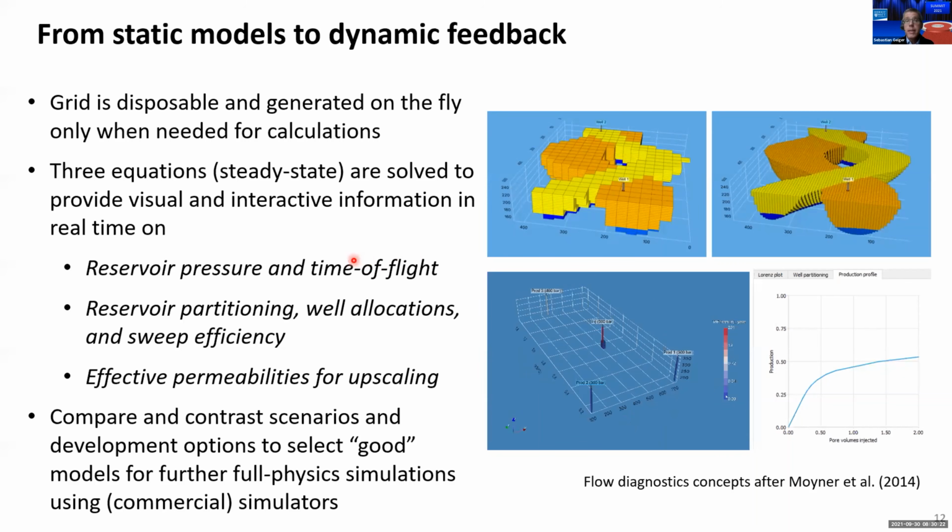We solve steady-state equations to provide visual and interactive information in nearly real time on the reservoir pressure, time of flight, the reservoir partitioning, well allocation factors, and sweep efficiency, and we also do flow-based upscaling for effective permeabilities. Essentially, we've implemented the seminal work that came out of SINTEF by Olav Møyner, Knut-Andreas Lie, and others into RRM around flow diagnostics on grids. This allows us, as we're building geological models and testing geological concepts, to get really quick feedback on the dynamic behavior of the reservoir.